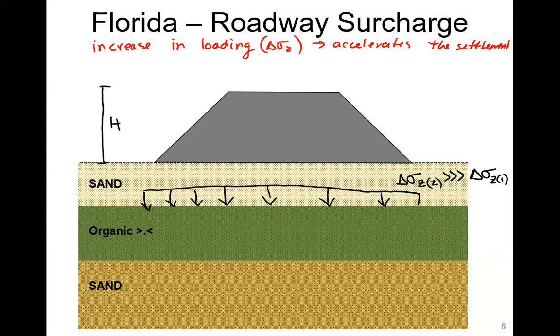So this is super important. But if we were just relying on Boussinesq and the 2-to-1 method, then we might not be able to fully capture what is happening in situ in this state. So for projects like this, the stress always needs to be monitored. There's a lot of monitoring, and not only once before the project and once after, but over time as well. So we're going to talk about all those things.